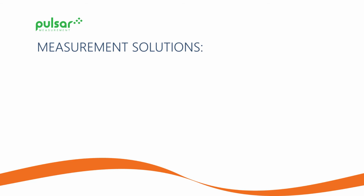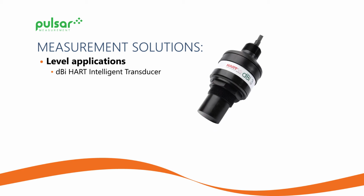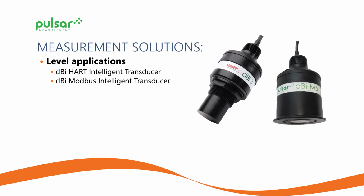As we've seen in stage 5, level measurement is an important measurement solution requirement. From here we would offer up our devices such as our DBI sensor, which is a loop-powered HART 2-wire device, moving through to various other products that can also offer digital connectivity using Modbus or Profibus.